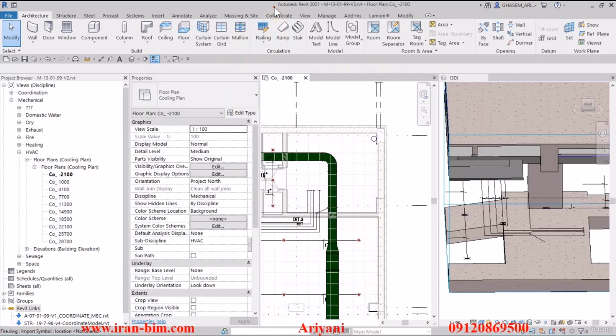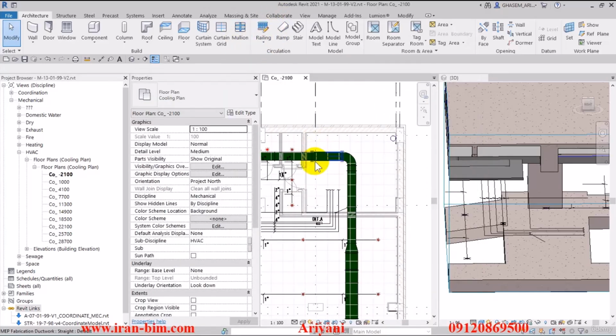But my point from all of this talk is that when you're trying to locate the shapes and the devices, and the brand that's going to be used isn't specified yet, you should try to choose the biggest family that's used in the making of the model. Or even if you're not choosing the largest one, try to choose one that's standard so you don't run into any issues later on in the performance parts, because you're going to have to assess the clashes and try to resolve them.